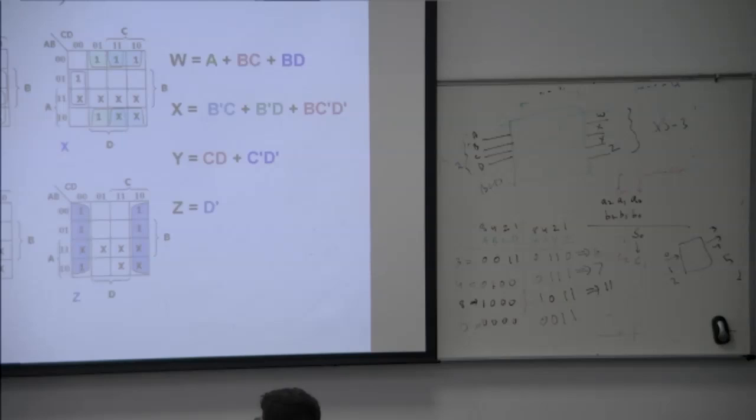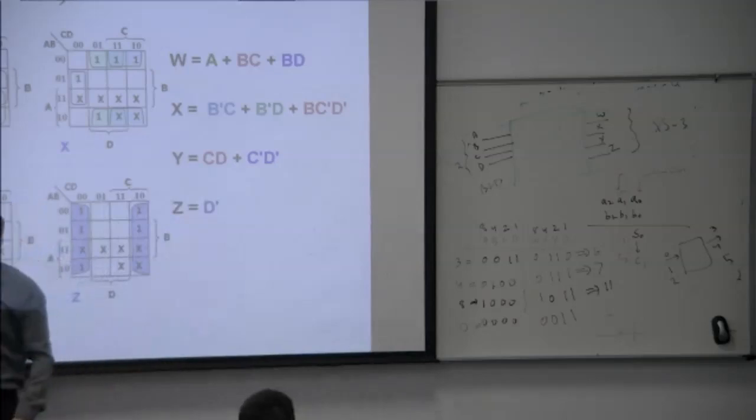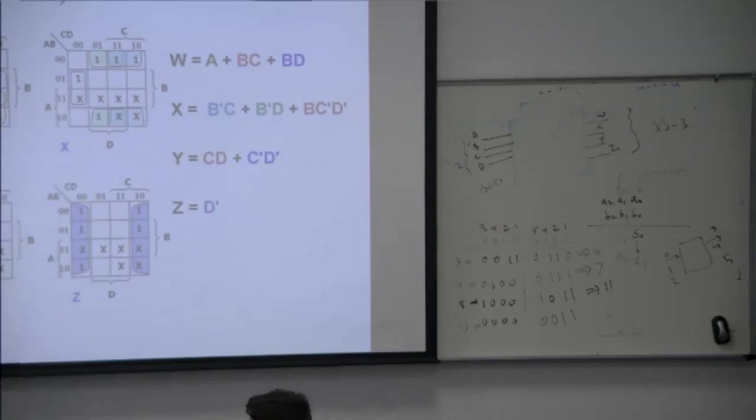Got it? Now, if you look at here, now we have used X as don't care. Can you see the color coding? Red, red. Then blue and blue. And this is all your homework. In the exam, I will not give you anything. So this is an example. Design, convert a BCD to XS3, and then you do all the things.